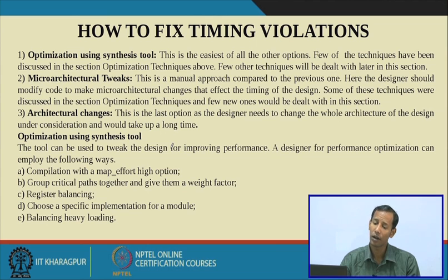Then architectural changes. Suppose for one adder design, there are several adder designs like carry save adder, carry skip adder, carry lookahead adder, ripple carry adder. There are several adders available, that means different architectures. They do the same operation, addition, but there are several architectures.